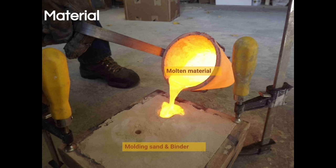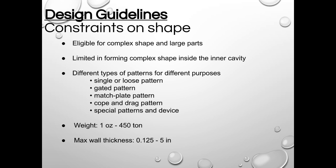A wide range of molding sand can be used for different materials, including silica sand, olivine sand, chromite sand, zircon sand, and chamotte sand. The sand is combined with binders such as clay and water, oil, resin, or sodium silicate. Here are some guidelines to help the process. Sand casting can form complex shapes and is able to produce large parts, but it is limited in forming complex shapes inside the inner cavity.